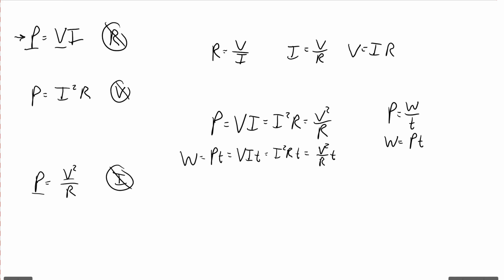In the first one, it's a direct relationship, but here the voltage is being squared, so it's an exponential relationship. So which one are we going to use? If you're doubling the voltage, does the power double, or does the power multiply by 4? And that's where that third piece of information comes in. They wanted you to keep the resistance the same. So it's not just voltage and power. They want to make sure the resistance is in the equation.